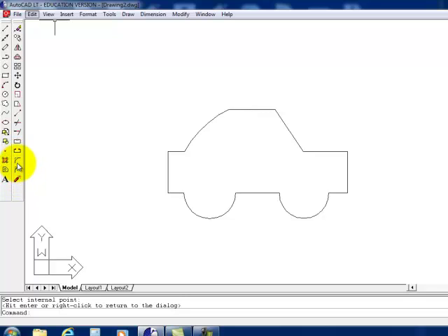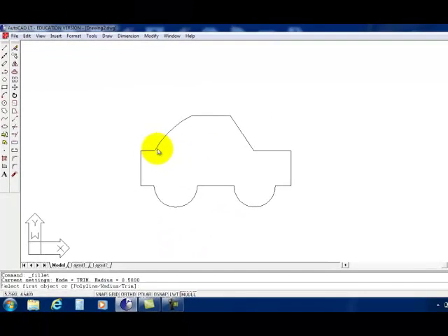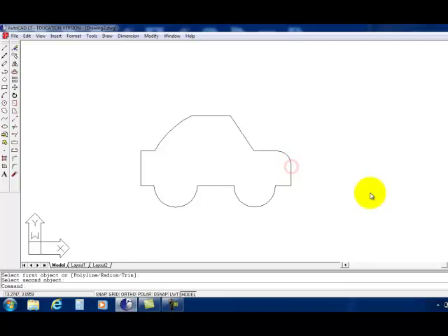Oh, the last thing I want to show you was to round off or to chamfer. Okay, so in rounding off some corners, we call that a fillet. All right, so if I wanted to round off this corner, it's going to round it off at a radius of 0.5. That's fairly big for the size of model that I have. Let's see what it'll look like. So read your command line here. It's telling me select the first object, which is this one, and my second one, which is this one, and it just rounded it off in the front like that.